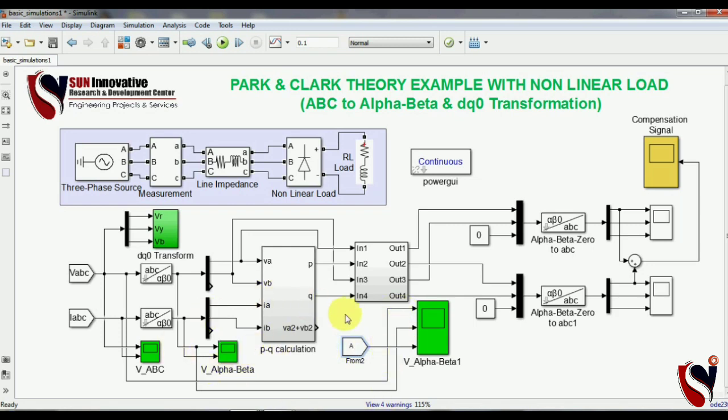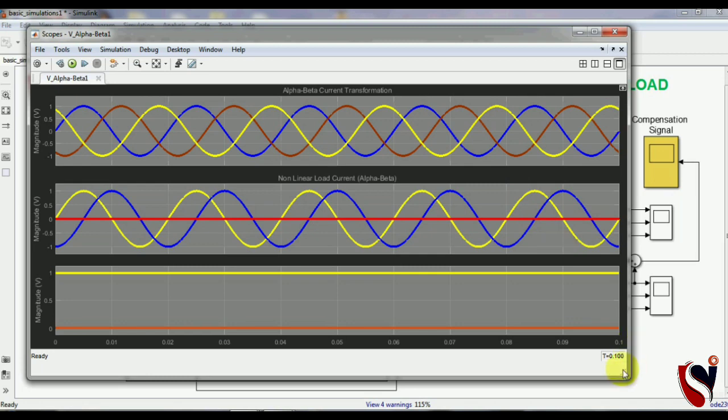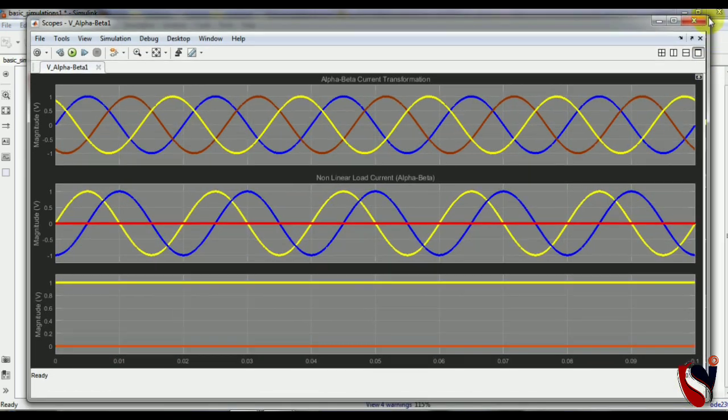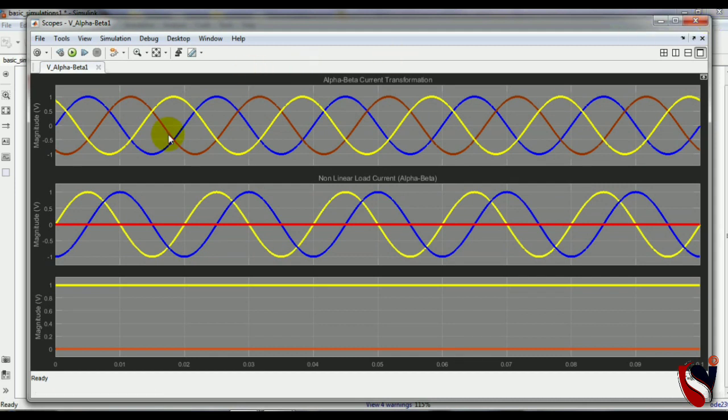This is the final graph of our video, the first graph is the 3-phase system, and it needs to be converted to the 2-phase system. Here you can see the voltage signals, and you can see the red line, the 3rd phase, becomes 0 here. So first this 3-phase system is converted to the 2-phase, and then this is the dq.